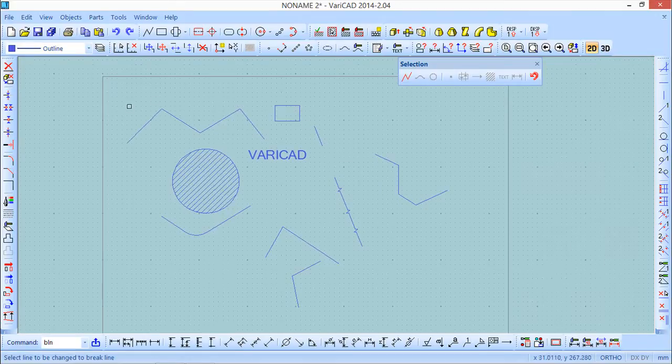An example: if I want to represent a part that was bigger than my format, I could use this kind of symbology in the middle of the part, saying that, okay, this is very big, so it has a couple of meters, for example. I just want to show the end and the initial portions, and in the middle it doesn't matter because the section is the same and the size is too big, okay? It's a graphical sign.